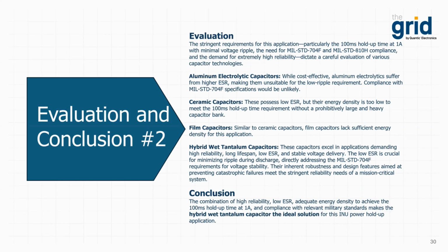Now, ceramic capacitors do possess low ESR, but their energy density is too low to meet the 100 millisecond power holdup requirement time without a large and heavy capacitor bank. Now, similar to ceramic capacitors, film capacitors lack sufficient energy density for this application.